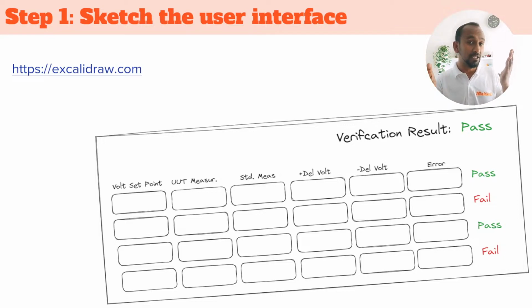But in case of the standard measurements, I can connect my PC to my measurement device, like a digital multimeter, when we take the Agilent 34000 series. It allows direct communication. We can connect to that DMM and start receiving the data. So we are going to see one such example of how it is done.